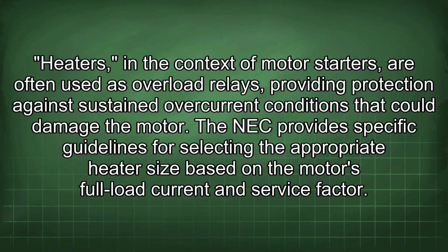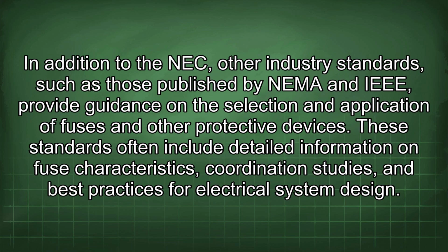The NEC provides specific guidelines for selecting the appropriate heater size based on the motor's full load current and service factor. In addition to the NEC, other industry standards, such as those published by NEMA and IEEE, provide guidance on the selection and application of fuses and other protective devices. These standards often include detailed information on fuse characteristics, coordination studies, and best practices for electrical system design.